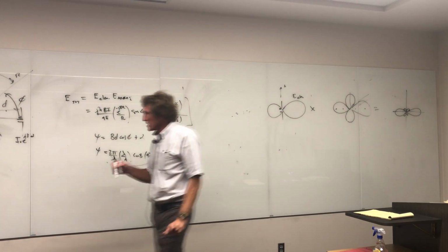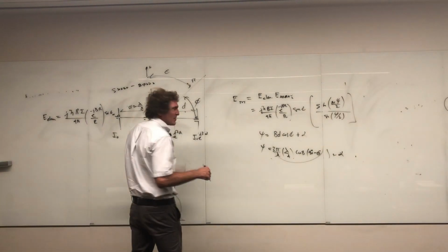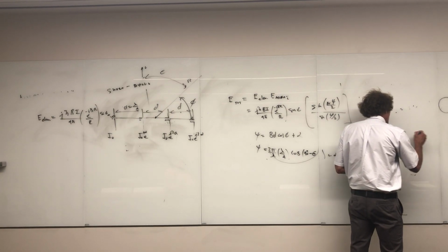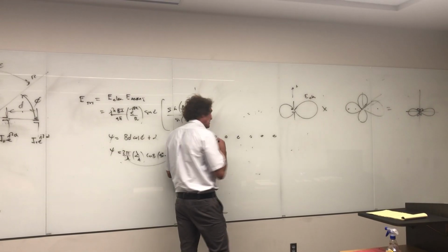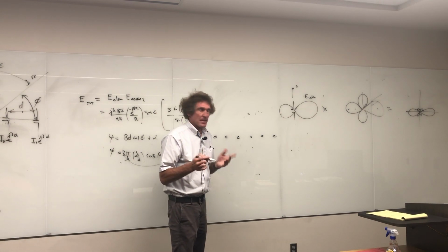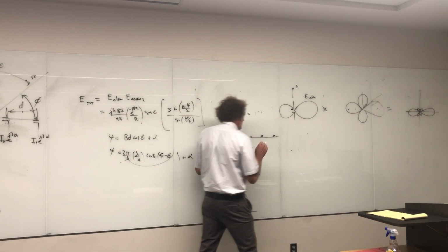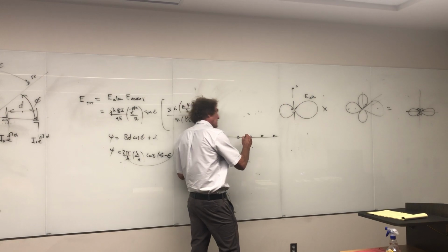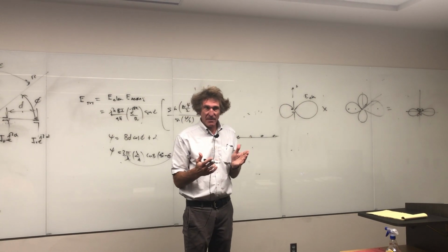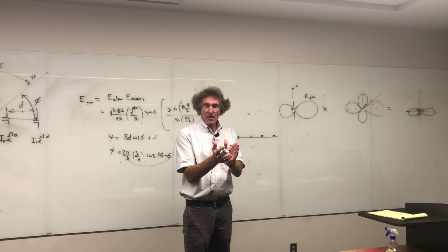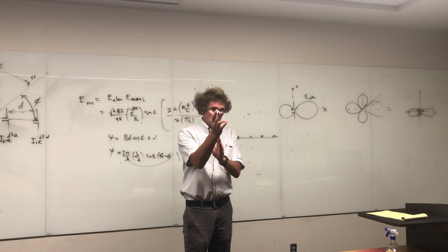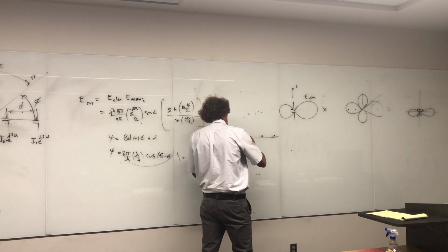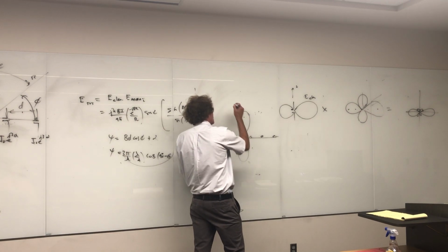Now here's some terminology that you have to get used to with antennas in general. When you have an array of antennas, regardless of what the array consists of, they could be patch antennas, loop antennas, short dipoles, it doesn't matter, they always talk about the vector direction of the array as the key thing. The main beam in all antennas, you're going to have a normalized antenna power pattern or E-field pattern that is maximum. It has the largest value. If the main beam, and it has a certain beam width, is perpendicular, if this would be the antenna pattern, that's called broadside.